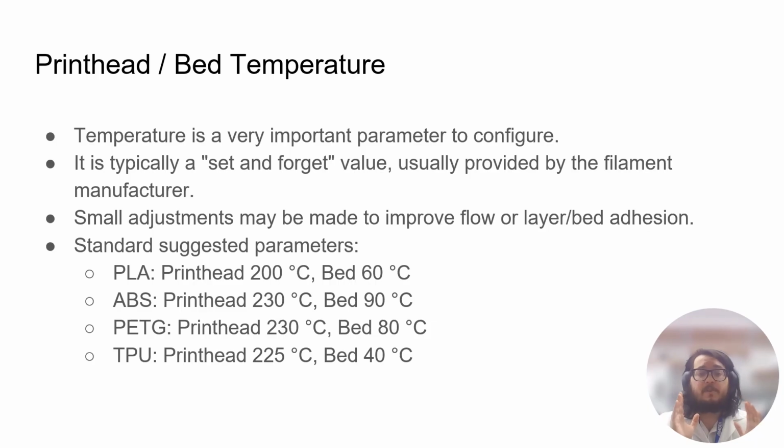If you have a 3D printer and you see, for example, a different value on ABS, for example, seeing the bed temperature being 100, it's not wrong, because each printer will have some different needs, or each filament that you use will have those different needs. But typically, you find the temperature that works for that type of material, PLA, for example, and then you buy any brand, it's typically going to work very nice.